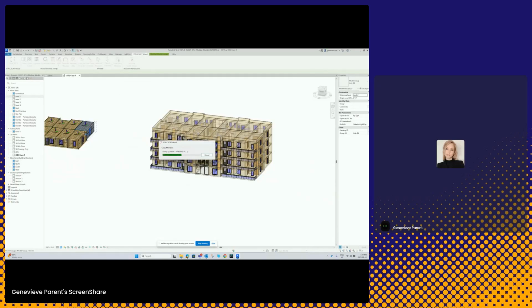And now what it's going to do, it's going to push all of the framing configurations over to these child groups. And this is why it's important to not copy over any join configuration markers. Because if we push all that information, it's going to be like it's reading multiple join markers. And we really only want to push the framing into it.